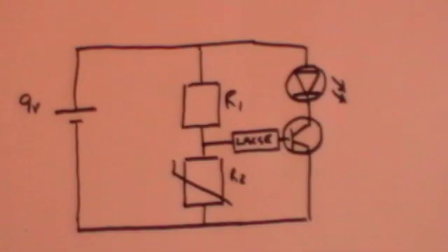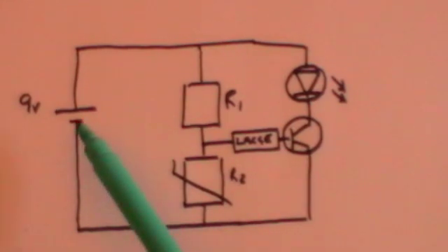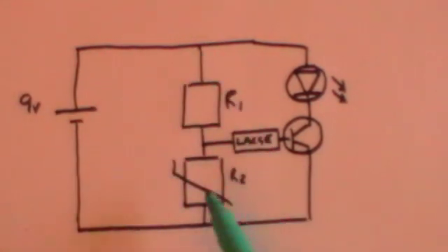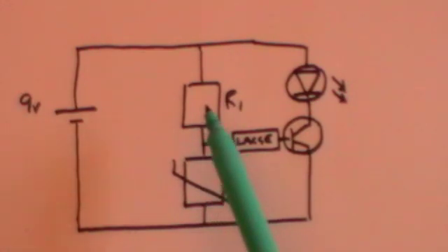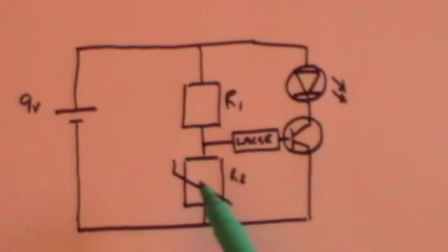So how is that going to help? Well, here I've drawn a circuit diagram, and I'll give you an example of how it helps. Well, it's quite simple. We've got a 9-volt battery. In this arm, you may recognise this, we saw this when we did potential dividers. We've simply got two resistors. A fixed resistor, R1, but here we've got a thermistor.